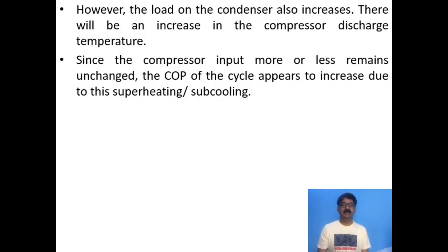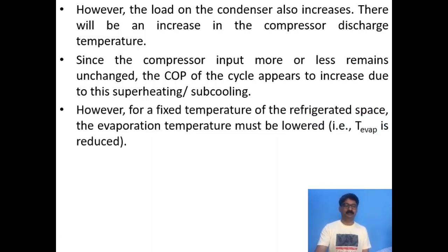Since the compressor input more or less remains unchanged, there will not be much change in the work input required for the compressor. The COP of the cycle appears to increase due to this superheating and subcooling. So the ultimate effect on the performance is an increase in the COP.